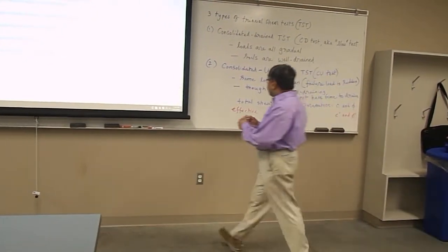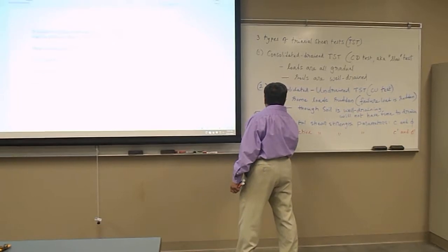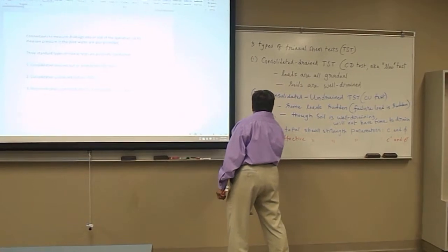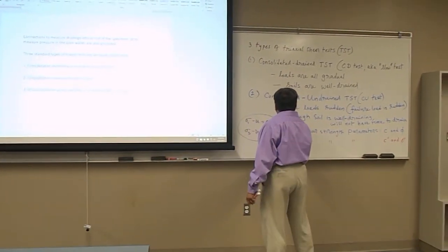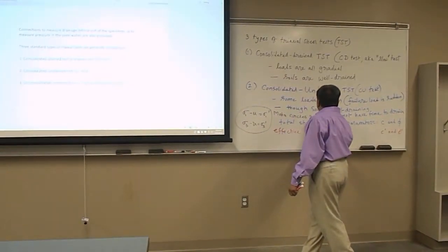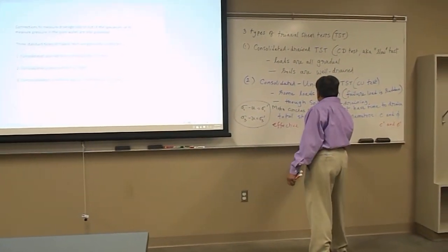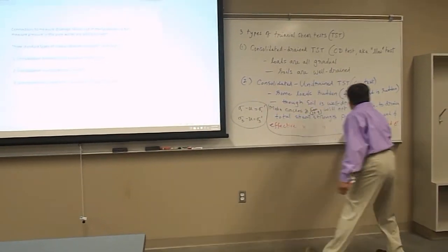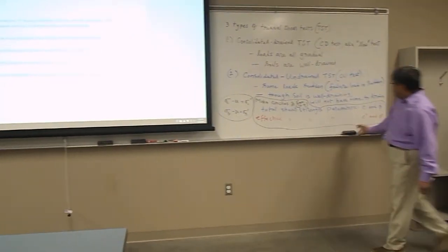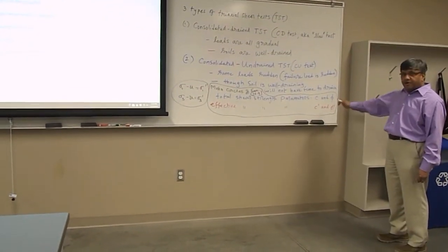That means first we subtract u from sigma 1 to get sigma 1 prime, and sigma 3 minus u is sigma 3 prime. From these two things we need to draw either Mohr circles or use equation 10(9) to get these two sets of soil properties for use in design and construction. I will follow it up in the next video.